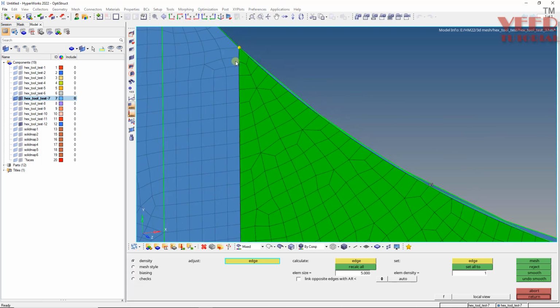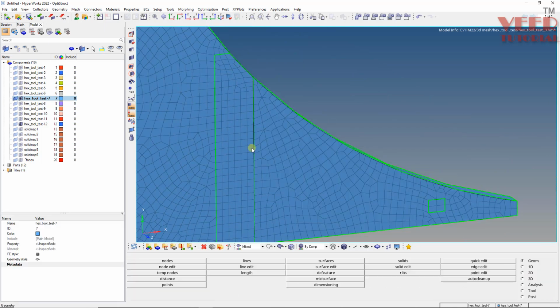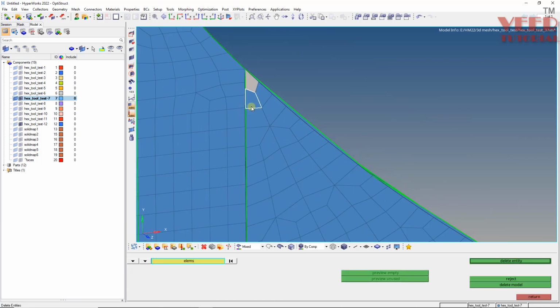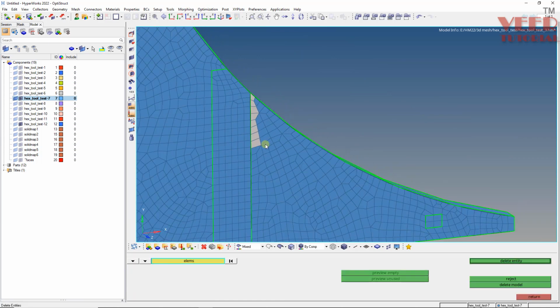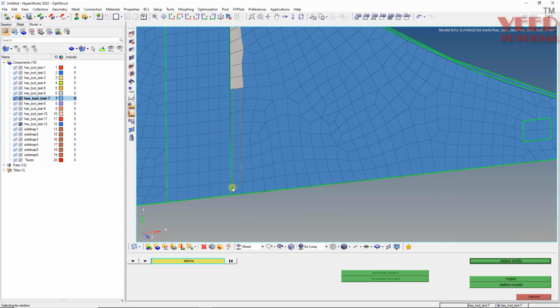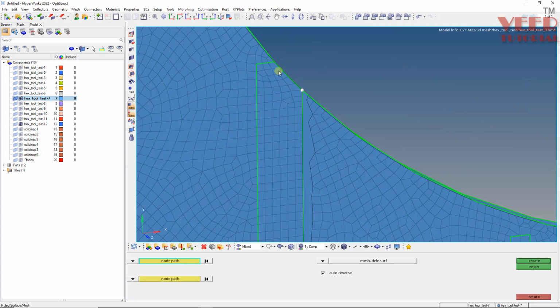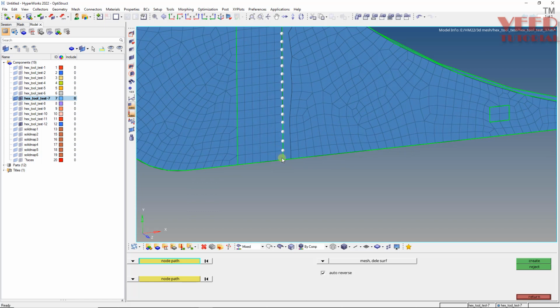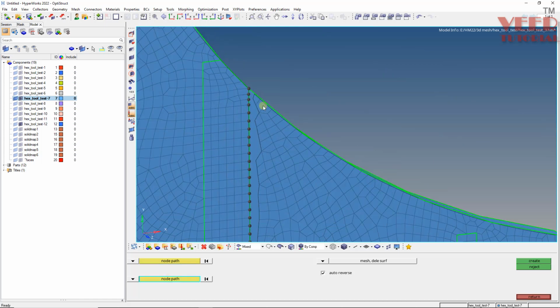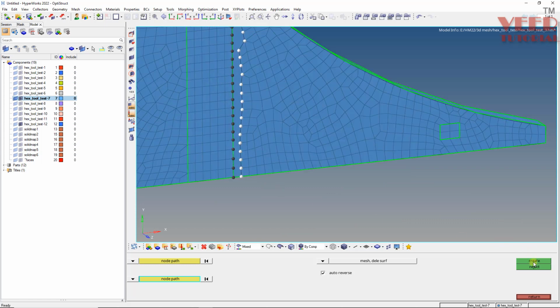Again here connectivity is missing, so we have to do this manually. Okay. So now once again delete this row of elements like this. Delete. Then go to ruled from here to here, and once again from this node to this node. Here create.